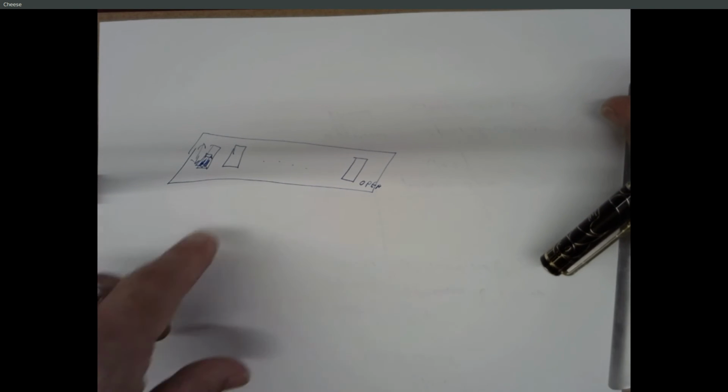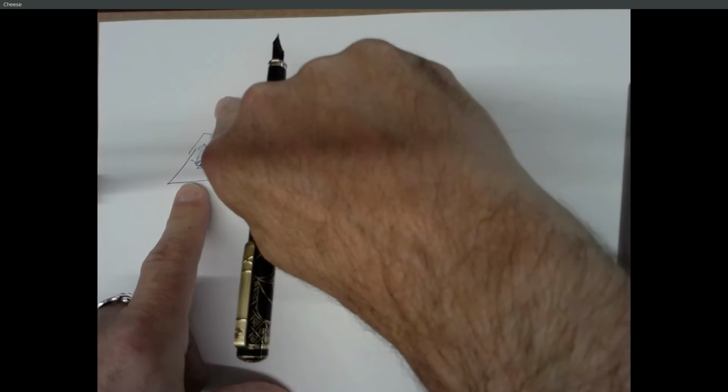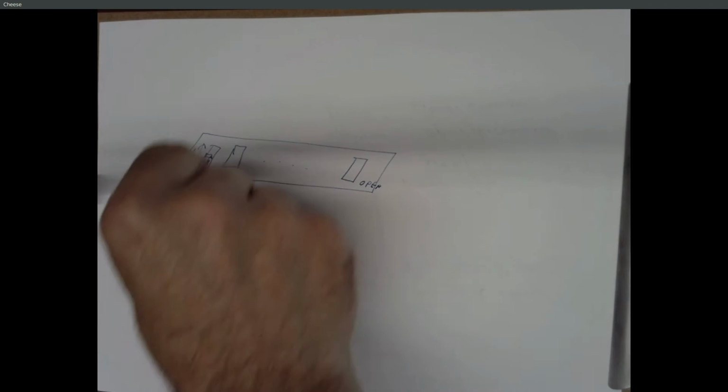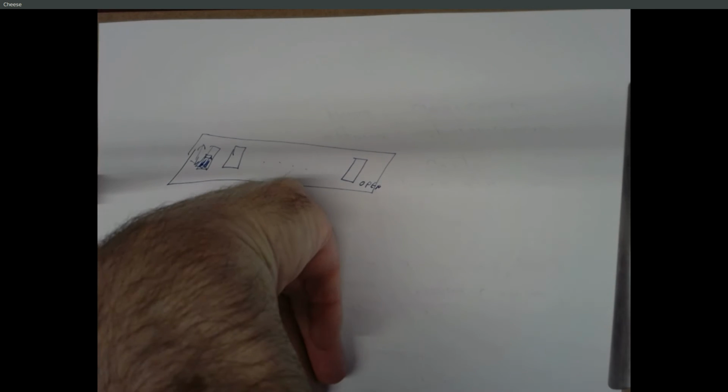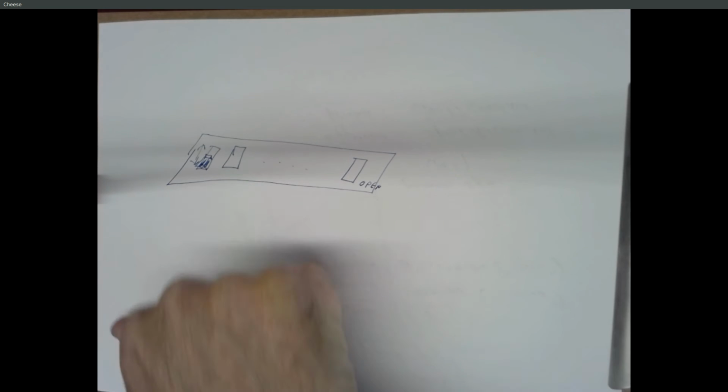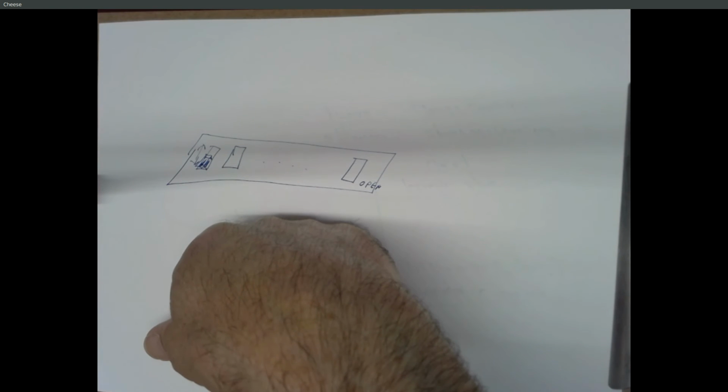So when you start messing with these switches, a suggestion is get a multimeter, put the switch in your protoboard, hook some wires on either side, hook those up to your multimeter, put it on resistance, and confirm what happens when you flip the switch. Right? Because that's going to mean a whole lot more than any explanation I give you here. One position, the resistance is going to be 0. The other position, the resistance will be infinite. And it'll show some kind of error message on the display of the multimeter. Right, so make sure you know what those two positions are.